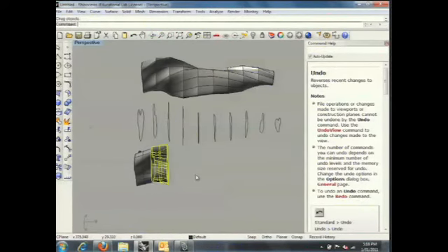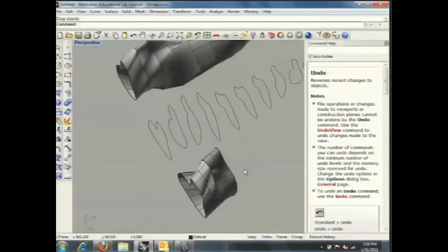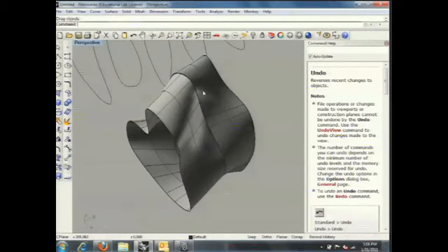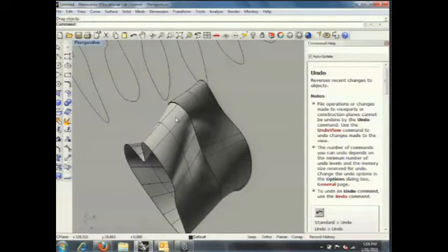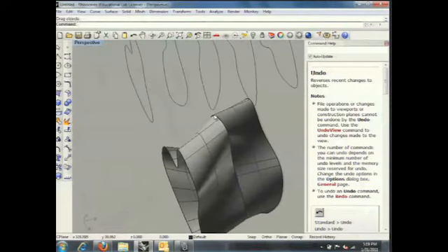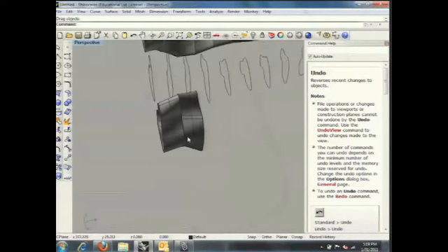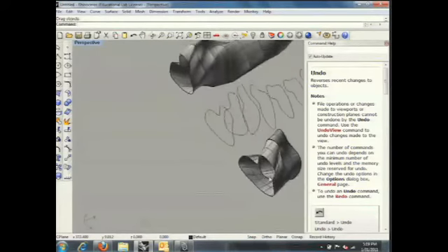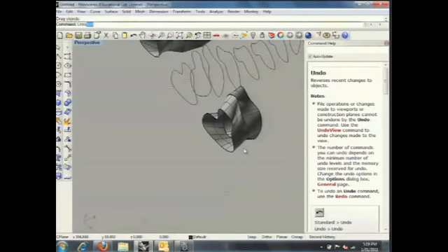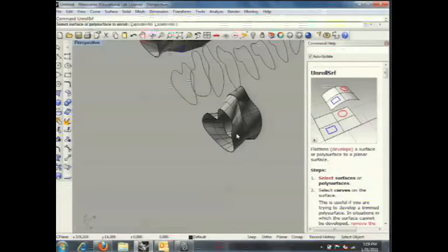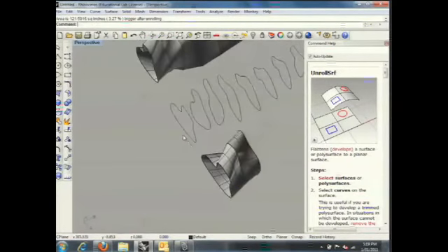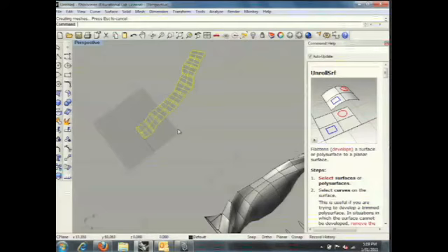And you might notice the difference of this approach is there's no continuity across these 2 surfaces, right? Also, the line is straight. So you can tell the degree along this orientation is 1, right? It's a straight line. Only in this fashion can you unroll. So let's do unroll surface. I can pick up this guy, enter, see what happened. You got this nice.